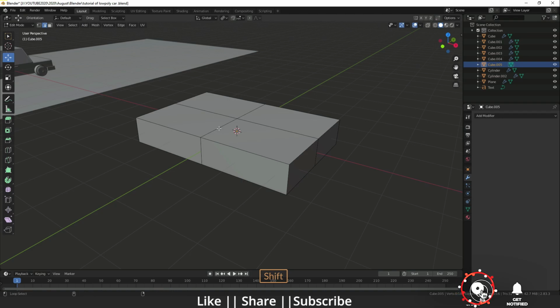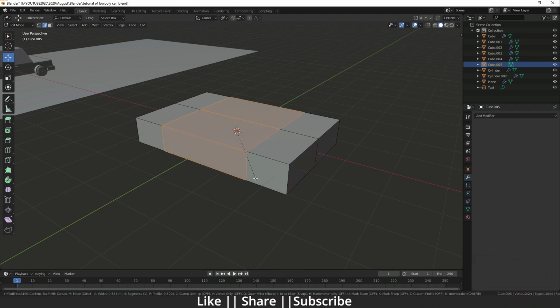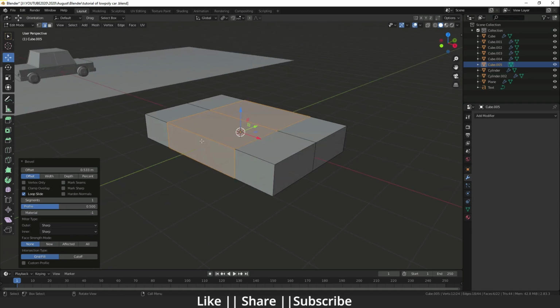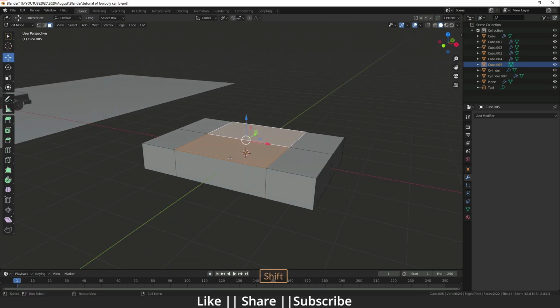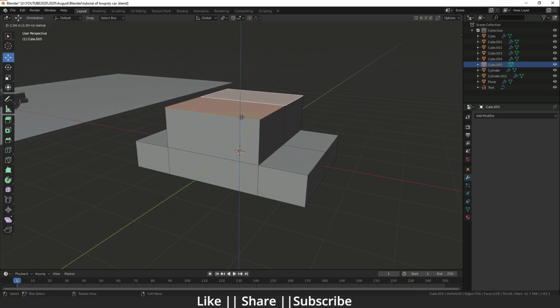Then after that I'm going to select that edge and press Control B for bevel like that, and I'm doing the bevel. Then after that go to face mode, select both faces and press E for extrude like that.